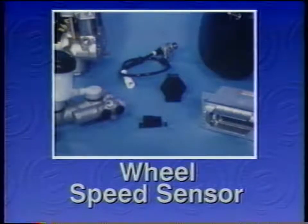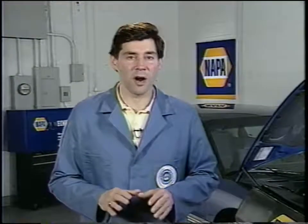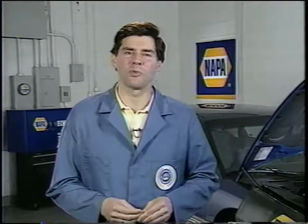The rear wheel sensors are not interchangeable, and the wheel or tone rings are not serviceable and must be replaced if damaged. Front wheel sensors are part of the wheel and hub assembly. The sensor is not replaceable, nor is the air gap between the sensor and ring adjustable.